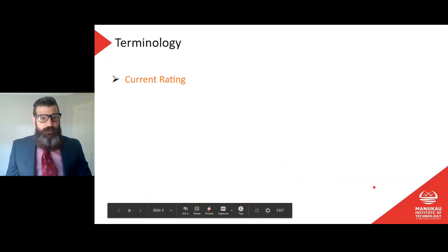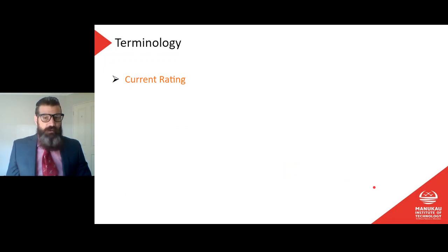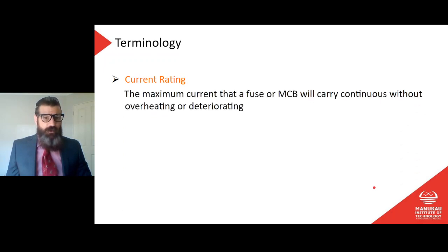Alright, let's have a look at some terminology. Current rating. What does the current rating of a circuit breaker mean? Well, or a fuse rather, fuse or circuit breaker. That's the maximum current that a fuse or MCB will carry continuously without overheating or deteriorating.